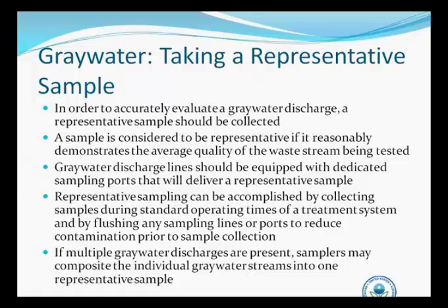If you do have a UV system installed, obviously the port should be after the UV apparatus, particularly because microbiology is involved. If you are collecting samples for microbiology, it's often a good idea to sterilize the port prior to collection. Some vessel owners use either heat to heat up the sampling port for sterilization or maybe spraying with alcohol. Either one of these is good.